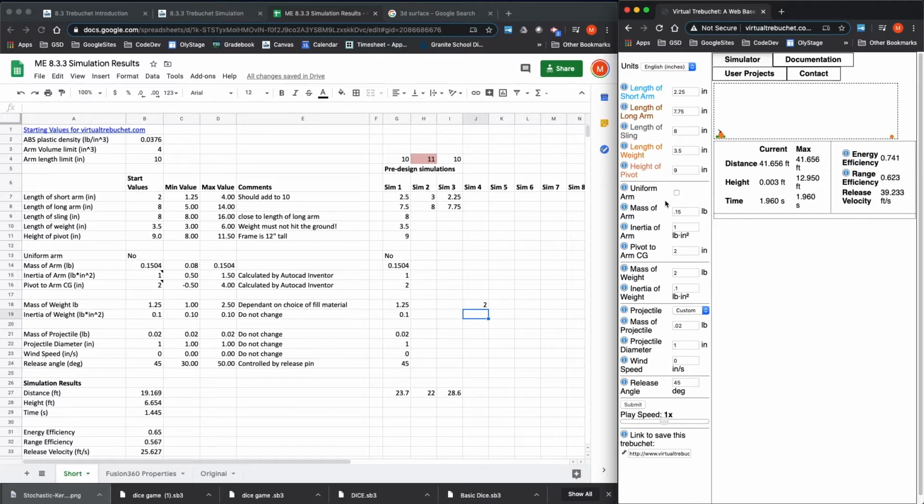If, on the other hand, you went down to the pedal on a bicycle and just spun the pedal, you would find that it will turn maybe once or twice and then it will stop. That happens to be a very low inertia design. Most of the mass is right there at the center, just very close to where the rotation happens, at the hub there. And that's also on purpose.